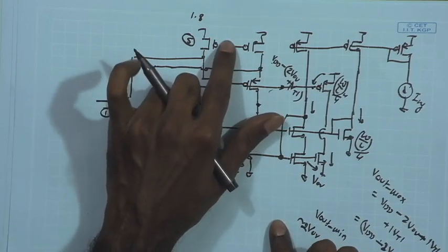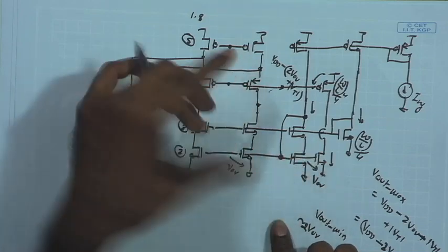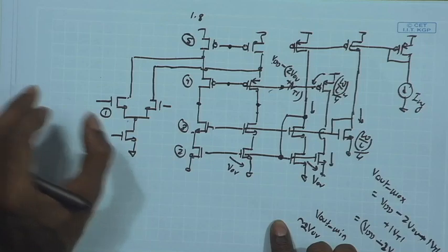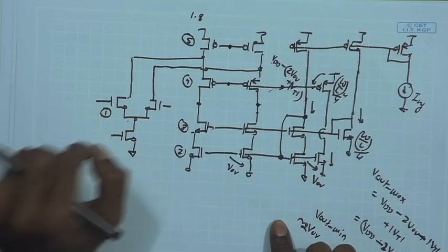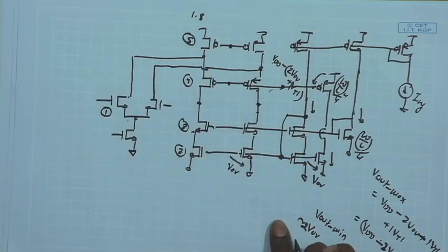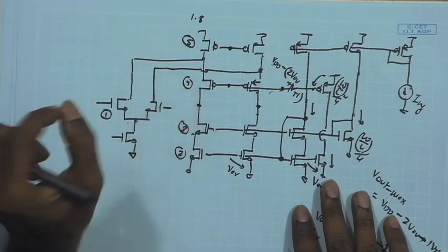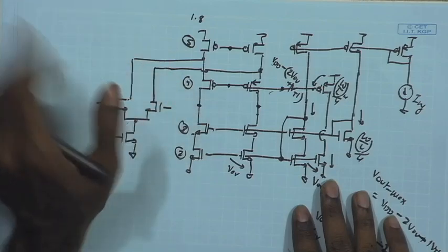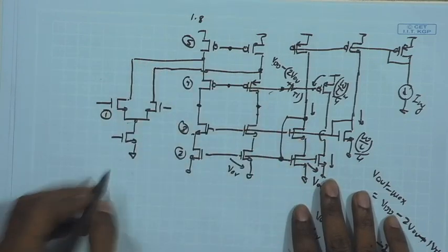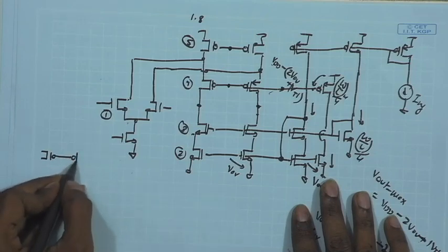And here we can see that again the bias point is supposed to be provided for the PMOS load, and therefore the gate voltage over here, the DC point of the output of the error amplifier, is supposed to be close to the DC bias point of this gate. Therefore it is advisable to choose an error amplifier with PMOS load, so that its output bias point under stable operation is close to the DC gate potential of the PMOS. Therefore, I will use a PMOS load error amplifier,